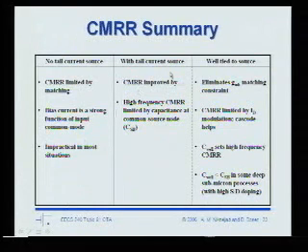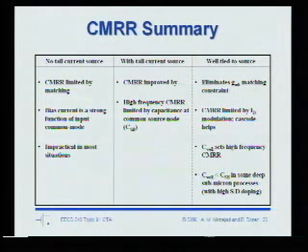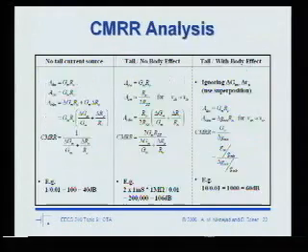With a tail current source, we improve the common mode rejection ratio, and at high frequencies, we're limited by that capacitance there. If we tie the well to the source, we get rid of this extra GMB matching constraint, but the well capacitance ends up hurting our high frequency performance. Okay. Any questions on this? All right. We have about 10 minutes.